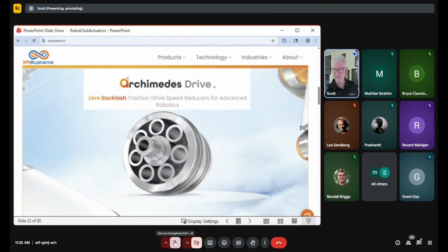And I'm going to look at this and say, man, that has zero teeth. And it kind of does, but at the same time, you could say it has an infinite number of teeth. One of the things that's nice about it is that even though it has zero backlash, there is a point where it slips. Technically, what happens a lot of times, and you don't want something like that, is that you get a torque that ends up breaking your system. So in this case, you really can't break anything. It will just slip. And there may be applications where, when you get too much torque, you actually want the system to slip